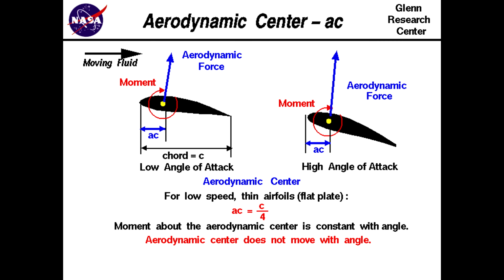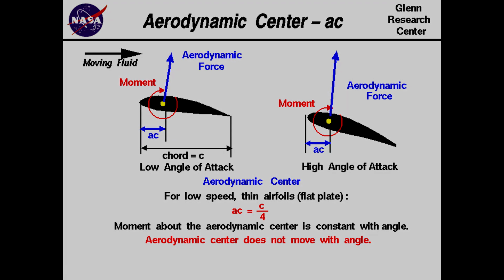So basically, if you receive forces, you can calculate the moment independently, right? By formula, you do not need to use Fluent, for example, to calculate the moment. You just put in the coordinates you want and the forces you already have. Just multiply forces by distance and you calculate the moment.